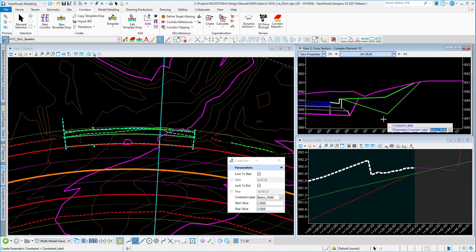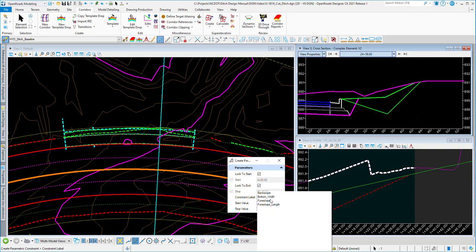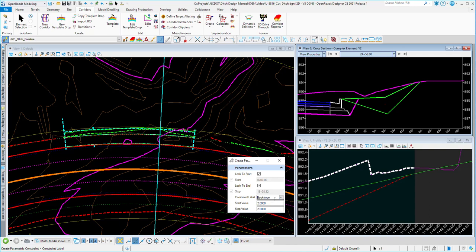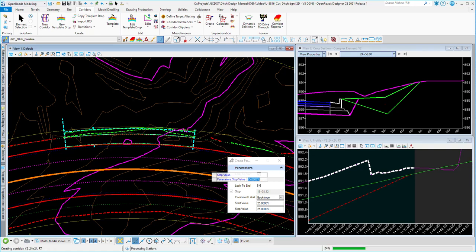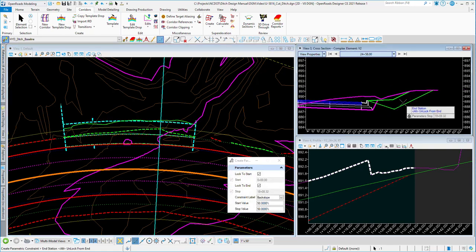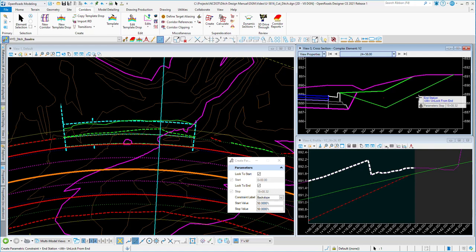And now you see my trapezoidal ditch is now a V-ditch. Now let's do the back slope. Sometimes you have to select a couple times to get it to change. There we go. So I want to change this to 25%, a 4-to-1 slope, to match the roadway model. And then data point to accept the inputs. And now I have a slope that's matching.